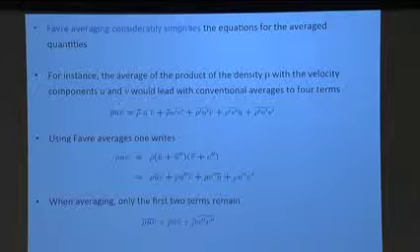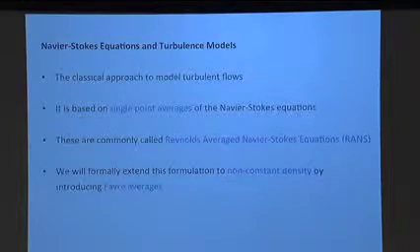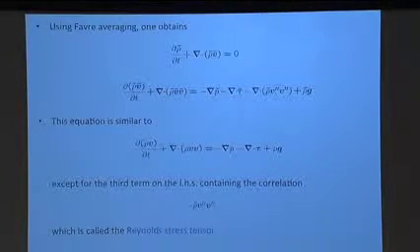Okay? And so, of course, the velocities are correlated with each other, which is why you get a term here like this. Okay, so introducing this then, you see here, this is a linear term, or linear in velocity. This doesn't change, just the same time-dependent term. This is a nonlinear term, so you get this term here and this term out of the advection term. Pressure, and this is the viscous stress, and this is gravity, and all of these are linear, and so they just look like in the undisturbed equation.